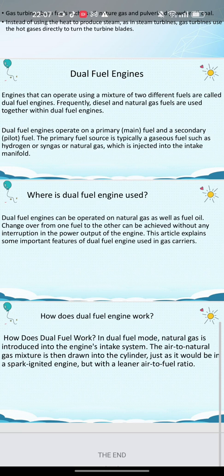Advantages of gas turbine: it is simple to design and construct compared to a steam power station since no boilers are required. Much smaller compared to a steam power station of the same capacity. Lower operating costs. Less water use since there is no need for a condenser. Maintenance charges are low. Can be started quickly. No standby losses.